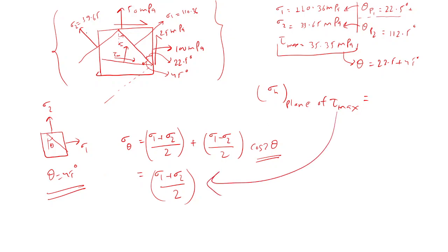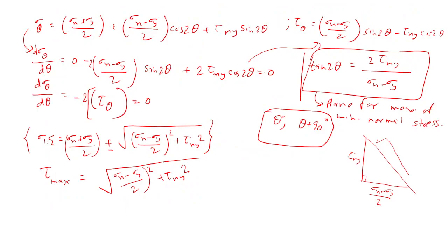So here sigma 1 we know, sigma 2 we know, and one thing I want to tell. In this formula, we know sigma theta, and now can you find sigma for theta plus 90? So what will come? Sigma y dash: sigma x plus sigma y by 2, then minus the same term.